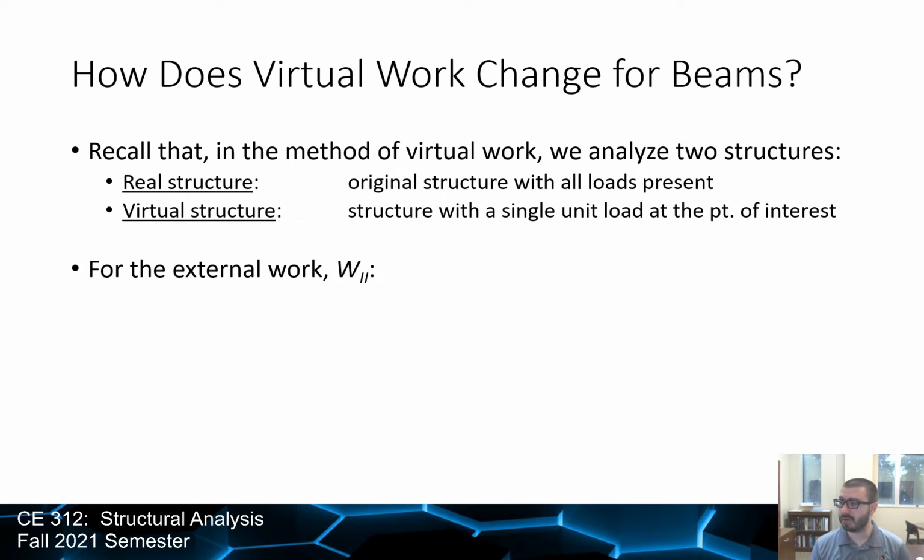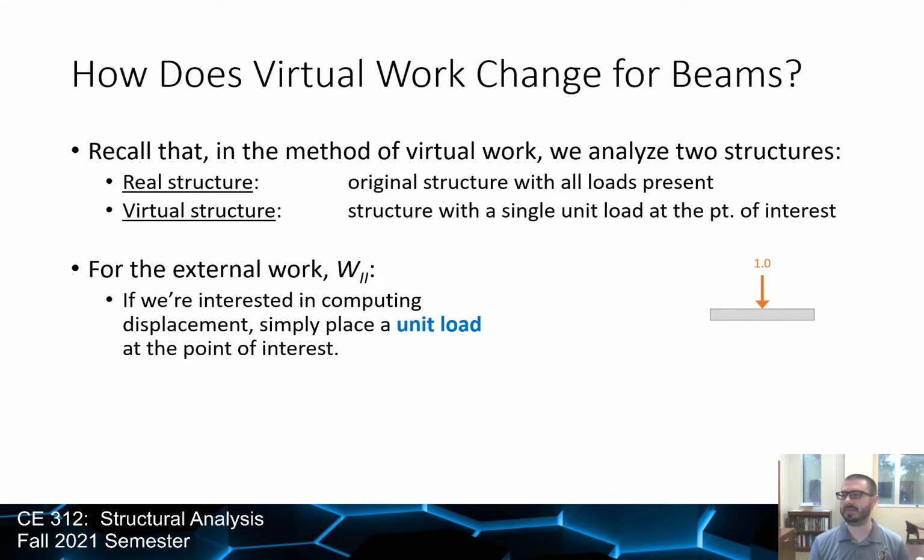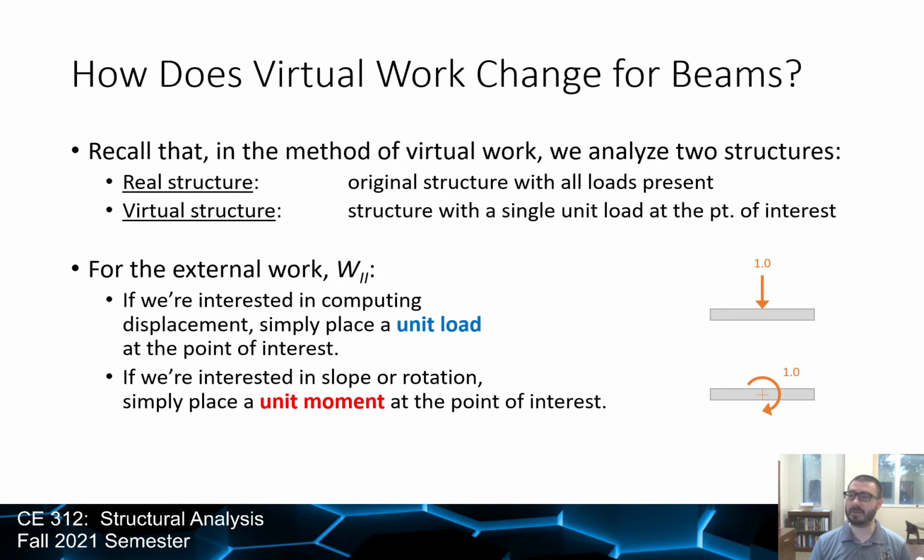For the external work, we're going to do basically the same thing. If we're interested in computing displacement, we place a unit load at the point of interest. And if we're interested in determining slope or rotation, we place a unit moment at the point of interest.